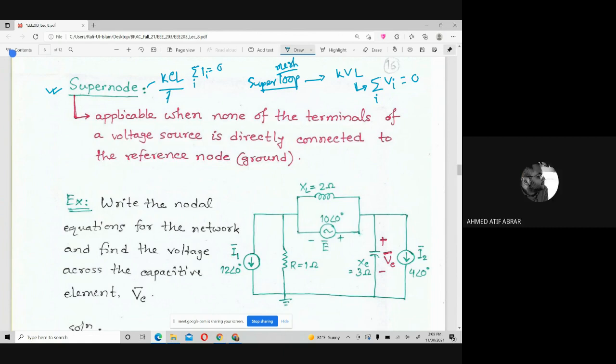Yes, sir. Okay, perfect. If this is the case, our target is to write down the expression for current. If the current is given, no problem, or we need to convert everything to current using this formula. For our case it is V divided by Z. So the summation of V divided by Z, or current, has to equal zero.